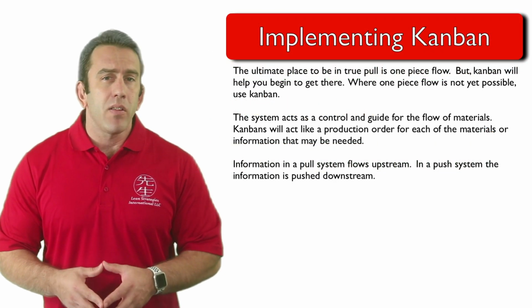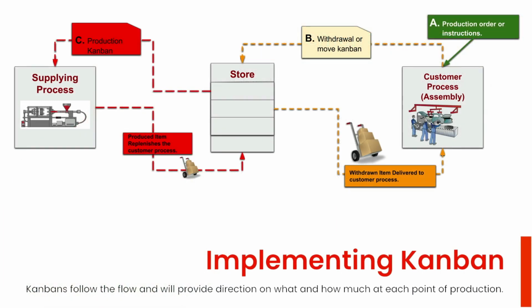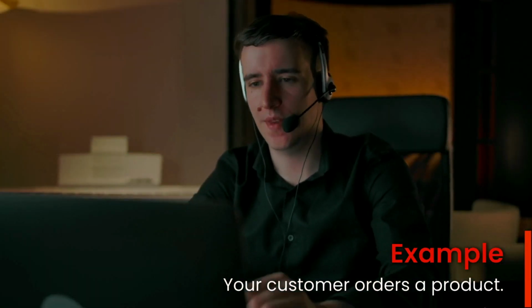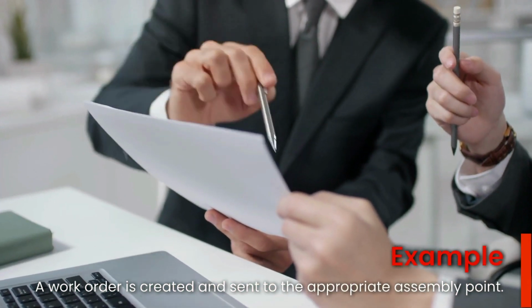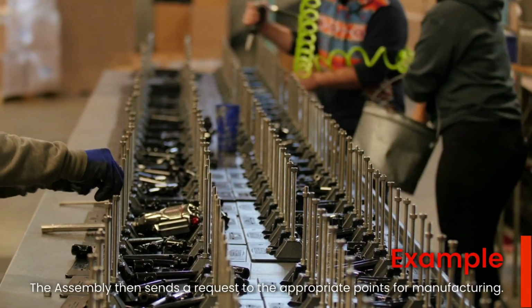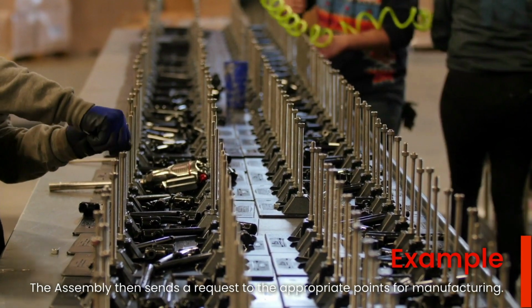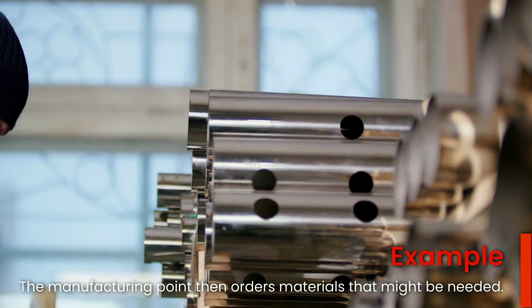Let's review the basic flow of the system. Keep in mind that a Kanban will follow the flow and will provide direction on what and how much point of production. Here's an example. First, your customer orders a product. Then, a work order is created and sent to the appropriate assembly point. After this, the assembly then sends a request to the appropriate points of manufacturing. The manufacturing point then orders materials that might be needed.